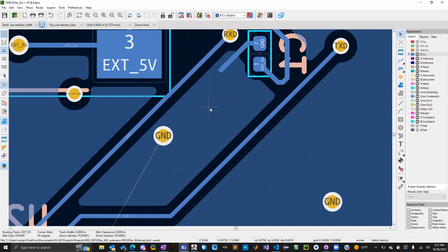Nine times out of ten, it'll make it worse because signals that you may not have made the connection about in your circuit design originally were using the whole ground in order to reduce EMI. But now that you slash the grounds in half, one's digital, one's analog, some of those signals aren't getting the same ground connection, so they have to take an entirely different path, and it's going to pick up more noise in whatever new path.